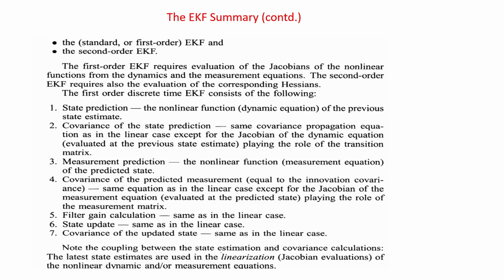Once you get the gain, you calculate Kalman gain times residual, that is your correction. That amount of correction needs to be added to your predicted state. You get your estimated state at t equal to k, and I minus K H times the predicted state error covariance will give you your estimated state error covariance. All of this is written here in words, what I just told in summary. So, you have only the Jacobian calculation. This is all about the extended Kalman filter.